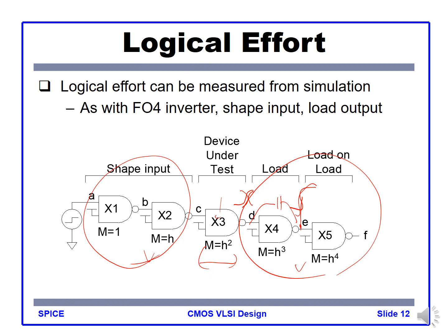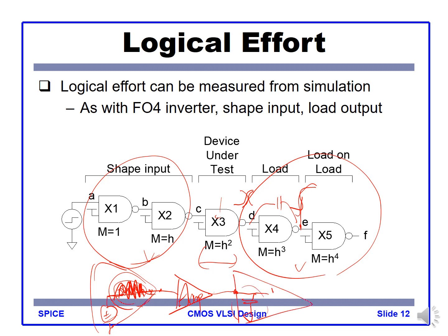This is very similar to analog circuit design. For example, when you have an amplifier design, even in analog, most students assume an ideal voltage source going into the amplifier, and then there's no load specified at the output. This actually cannot properly simulate the amplifier characteristic. You must use a practical input resistance, because the previous driving amp will have a finite output resistance, so you have to put some resistance there as the signal comes in. Also, you have to put some capacitance there, because the driving inverter will have an input parasitic capacitance, or load capacitance. You have to properly model the input and output network.